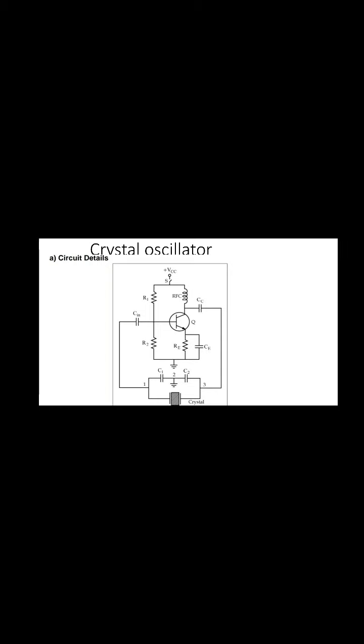If the frequency of the applied voltage is made equal to the natural frequency of the crystal, resonance takes place and the crystal vibration reaches a maximum value. This natural frequency is almost constant. The effect of temperature change can be eliminated by mounting the crystal in a temperature control oven, as in radio and television.